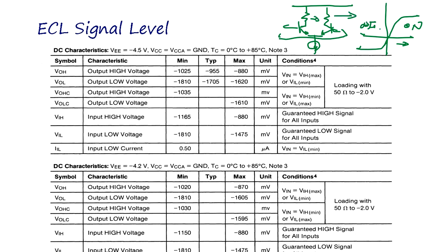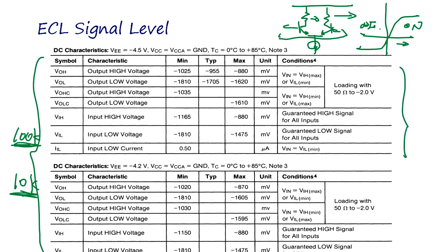But for ECL, the point is that this specification is the so-called 100K series made by Fairchild. Motorola initially made a 10K series, which is very similar, but 10K is not temperature compensated, so you have a table for each temperature range. It's very difficult to use. Fairchild improved it in the 100K series, so it's temperature compensated across the temperature.